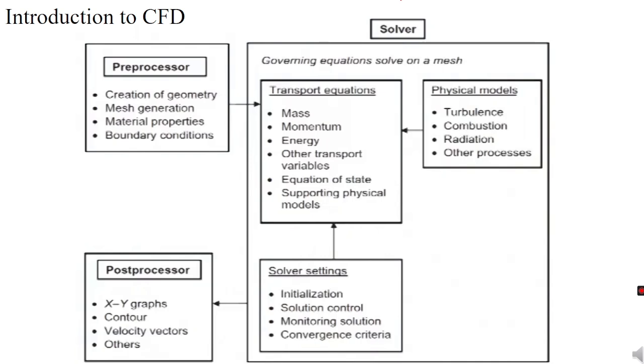An equation of state can be used to choose the system of equations. And then we can go for the physical model, whether we need to go for a turbulence model based on the flow characteristics. So Reynolds-averaged Navier-Stokes models, k-epsilon, k-omega, SST, or LES, large eddy simulation, for capturing the large-scale turbulence structures, or DNS, direct numerical simulation, for resolving all scales of turbulence, requiring very fine meshes.